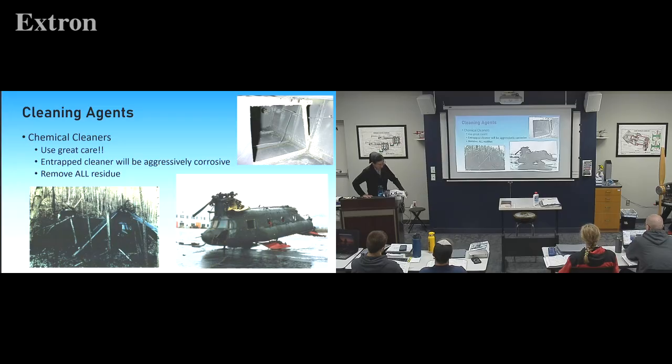The subsequent investigation suspected the cause of the accident was a fastener failure in the upper boost actuator due to hydrogen embrittlement from an unknown cause. However, we know that using unapproved or inappropriate cleaning fluids on aviation products can cause hydrogen embrittlement, corrosion, and other